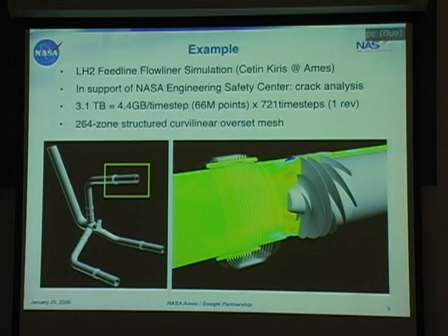And that brings the liquid hydrogen down. It trifurcates, and each one of those three subpipes feeds one of the engines. And at the end of each one, and we have one of them surrounded in a box, there's a relatively low-speed impeller. There's a close-up on the right, and that moves the fuel into a high-speed turbine that actually blows it into the engine.